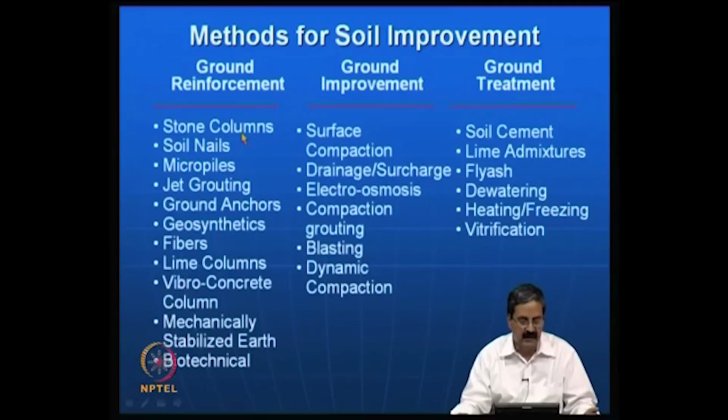Anyhow, jet grouting is a similar thing, where in grouting you are trying to put a stronger material into the system instead of the weaker material. Then we have another terminology called ground anchors. Particularly in the case of excavations, I will take you to some construction projects soon, where anchoring is done so that the retaining walls are stable or the excavations do not collapse, using ground anchors. We use an anchoring mechanism here, which is a very helpful thing.